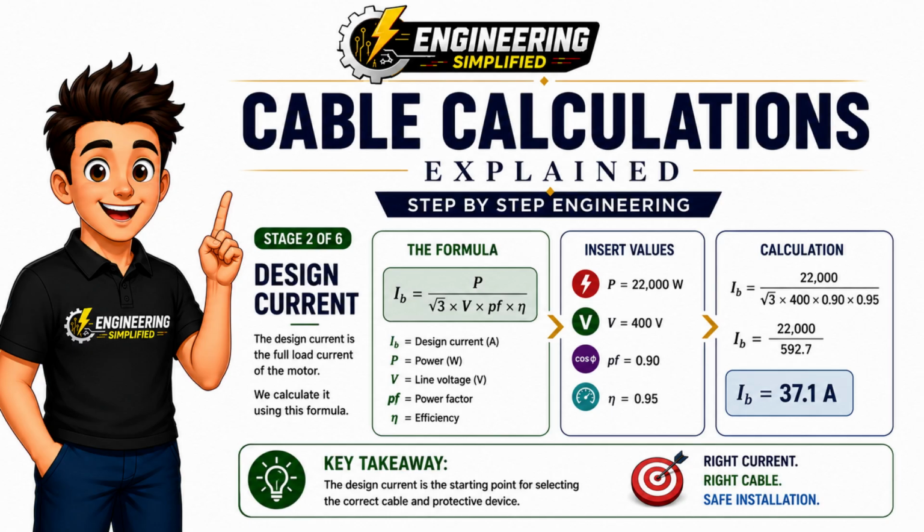Now we can calculate the design current. This is one of the most important values in the entire cable sizing process, because it determines the minimum current the cable must safely carry under normal operating conditions. Using the standard three-phase power equation, we substitute our motor power, supply voltage, power factor, and efficiency into the formula. After completing the calculation, we obtain a design current of 37.1 amps. This value becomes our starting point for selecting a suitable cable.